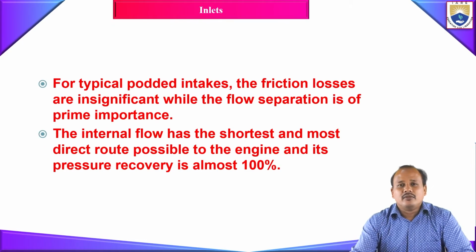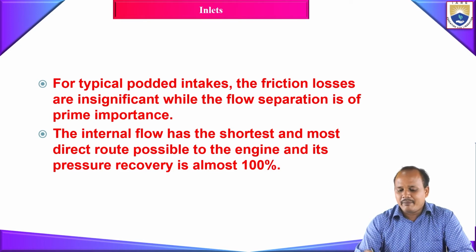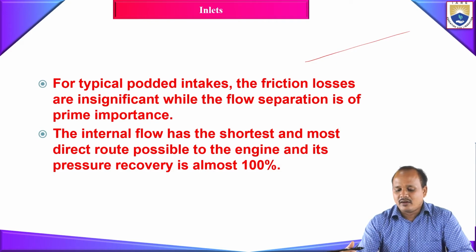Okay, so if you take a typical ported intake, what is the source of losses? Basically, it is going to be separation rather than frictional loss, because friction increases if the length of your wall is very high, or if the contact surface between your fluid and your solid wall is more and more, meaning you will have more frictional loss. Whereas in the case of your ported intake, the length of your intake is very small.